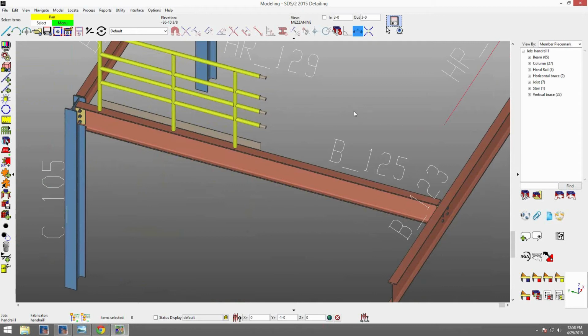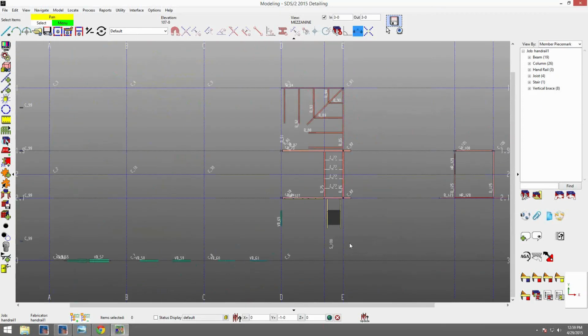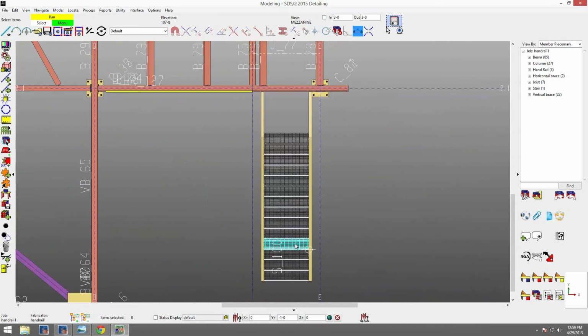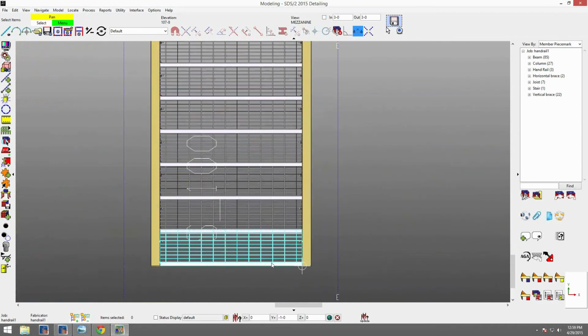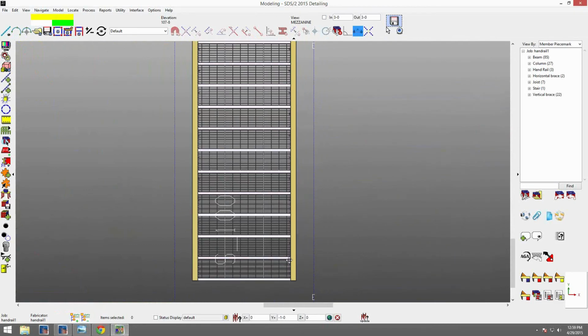The next handrail that we'll go through is a sloping handrail without returns. So I'm going to open up my mezzanine again. And I want to add in a handrail along this line. So since we add it, I'm going to add the handrail, so that's going to be where it's centered at. I want to center it on the gauge line of the stair stringer.